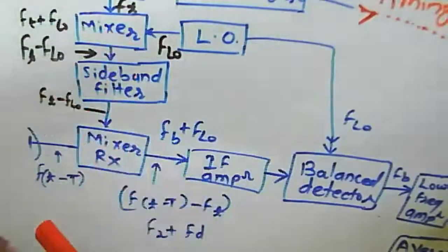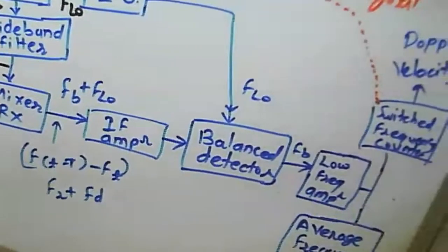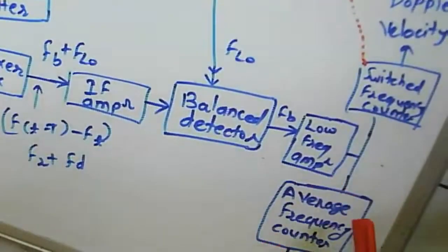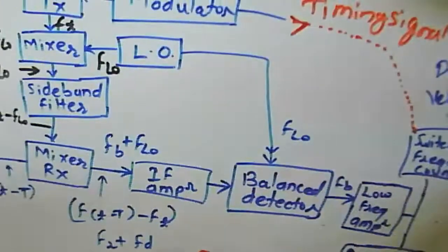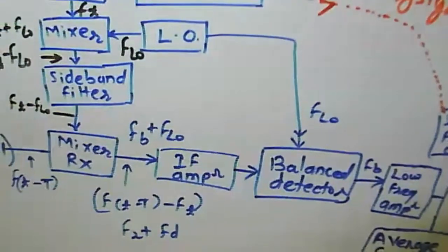Transmitting signal, we are receiving the echo, then we are having some noise there, as well as at the receiver we are measuring the frequency. We are supposed to use a frequency counter there. That frequency measuring device is used to measure the cycles: how many cycles in a given particular period of time, or we can say a modulation period.